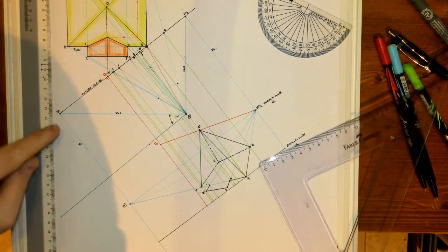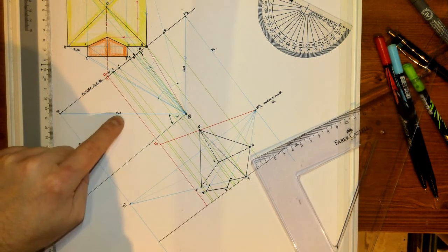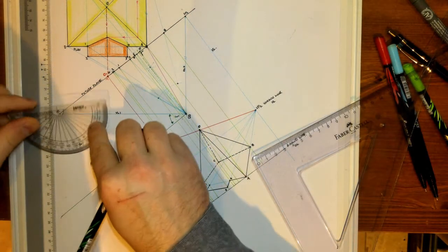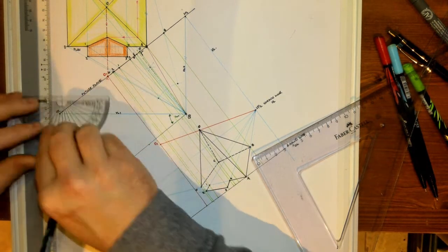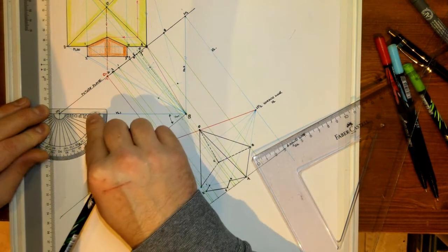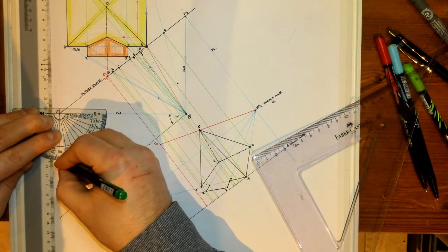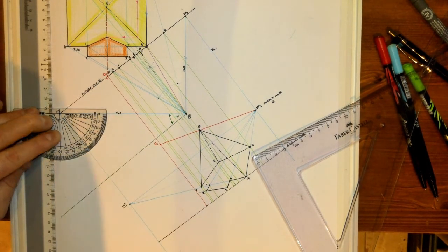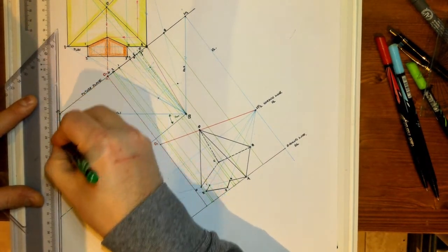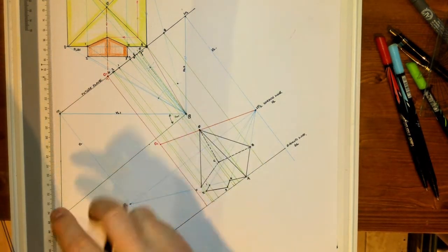Here's the thing, what we want to do now is from VP1 extend the line down that's at a right angle to the vanishing line, down to hit it. So in this case I'm going to use my protractor because I'm very tight to the edge of the page. I'm going to put my protractor on VP1, and line it up on the VL1 line. Okay, we're okay with that. From there I'm going to mark 90 degrees. Now I'm going to extend from VP1 down through that point I've just marked, on to hit the 40 degree line.